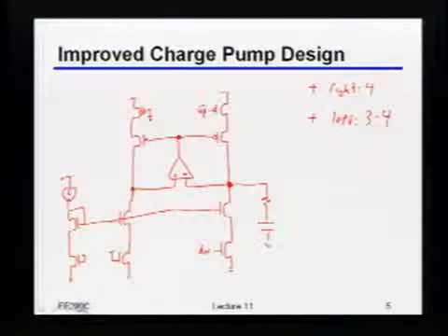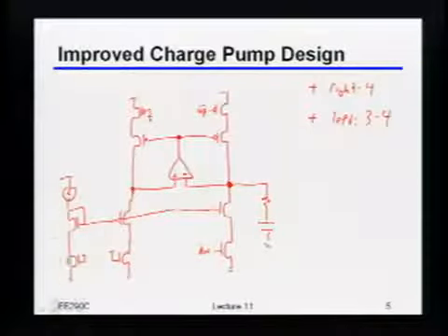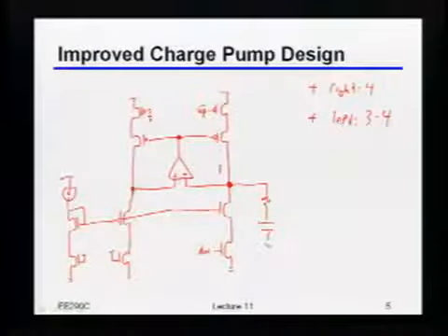Okay? So basically, there is indeed a positive feedback loop here. But the nice thing is the loop filter drops that impedance, A. And B, the PLL also says, no, sorry, that has to be a fixed voltage, at DC at least. Okay? Does that make sense to everybody?